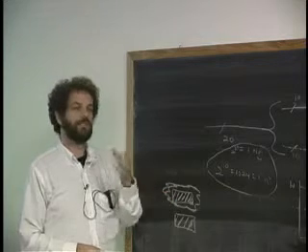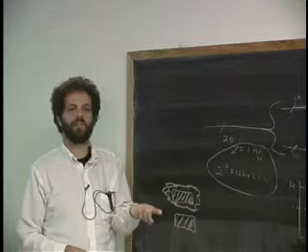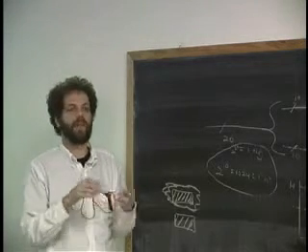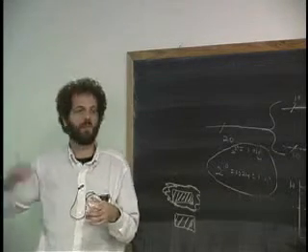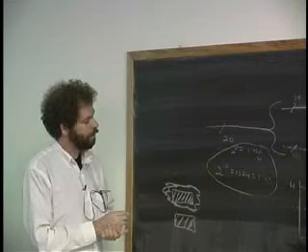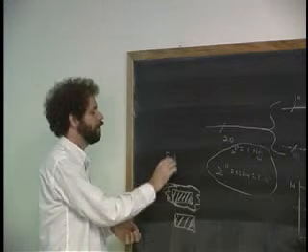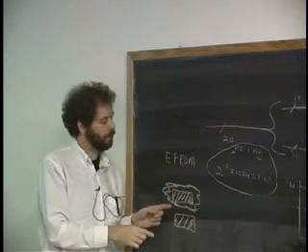Okay, and why a ROM, the cartridge you plug into your Game Boy, right? How the heck does that thing hold on to what it knows? Well, it turns out that there's two kinds. One's called a mask ROM, where they actually manufacture it. Some of them will have the switch closed, and some of them will just have the switch open. But the more common one is this thing called an EEPROM, Erasable Programmable Read-Only Memory. And it works like this.